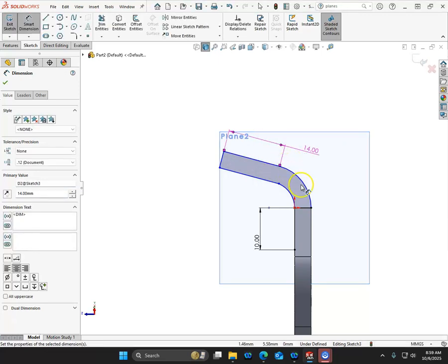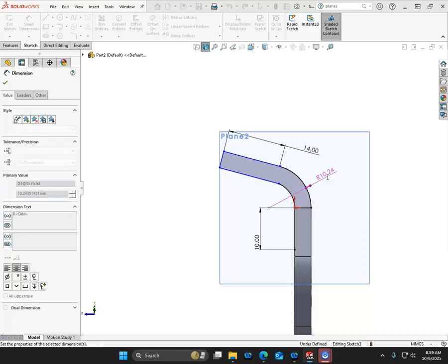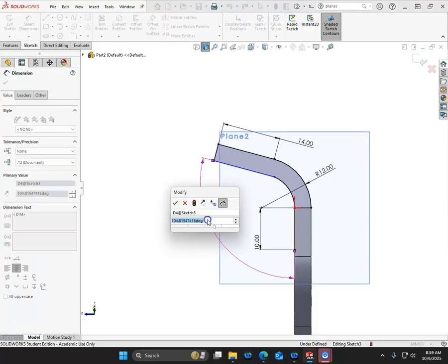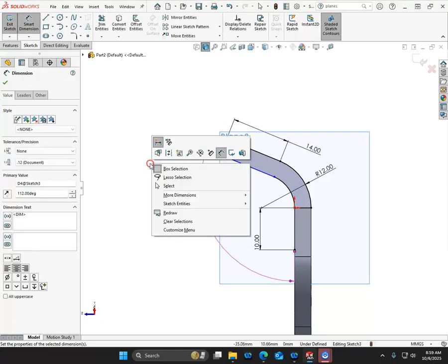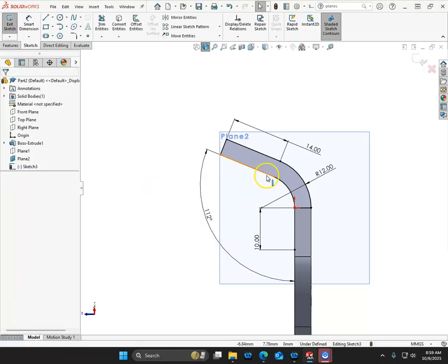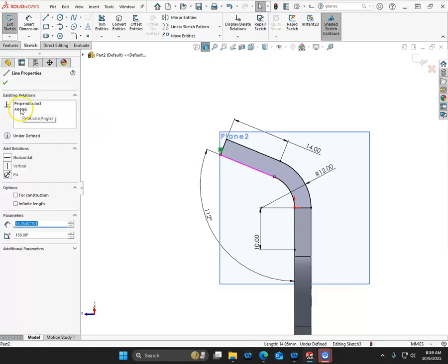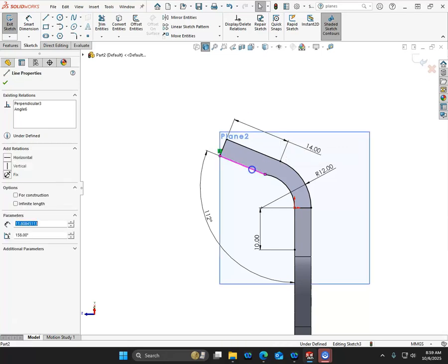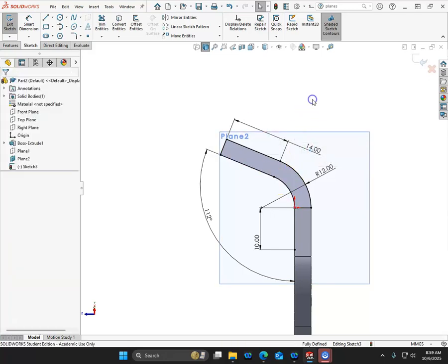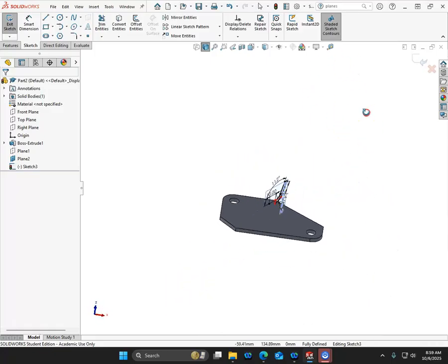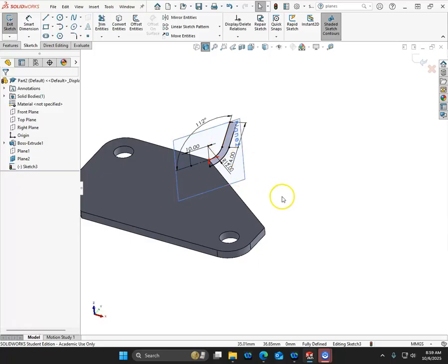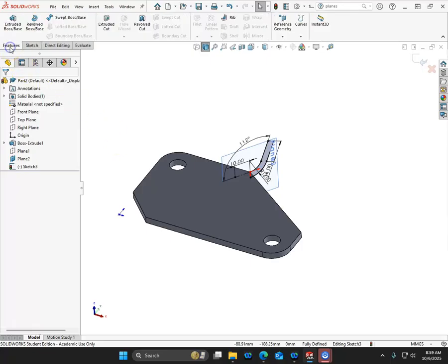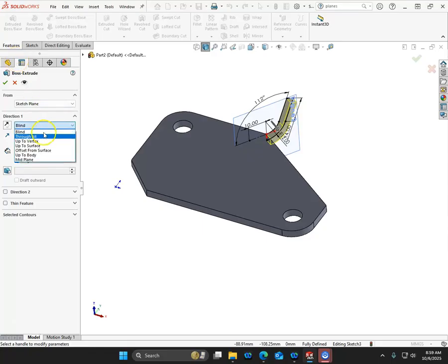All right, so move it around until you get that geometry in place. And then we have the 112. Center line's also going to help being able to define that geometry. All right, so we are missing more than likely a tangent. So I have perpendicular, the angle, and if I go to drag that, I'm going to see that it generates that sharp. So just more for experience than anything, tangent, dealing with lines and arcs, if you are underdefined, look for a tangency first.